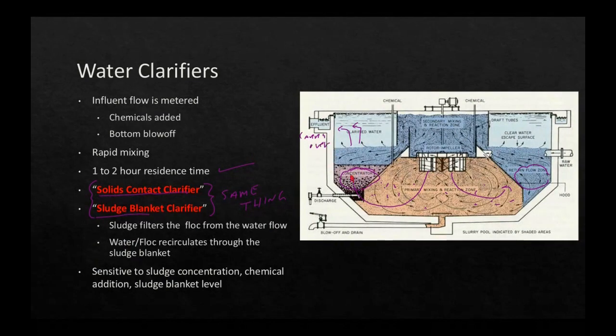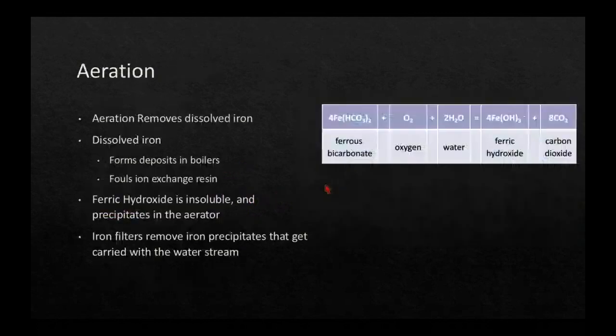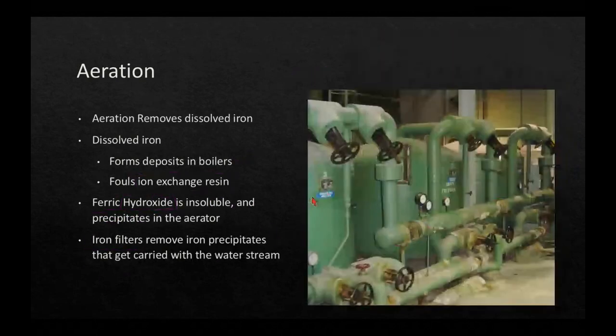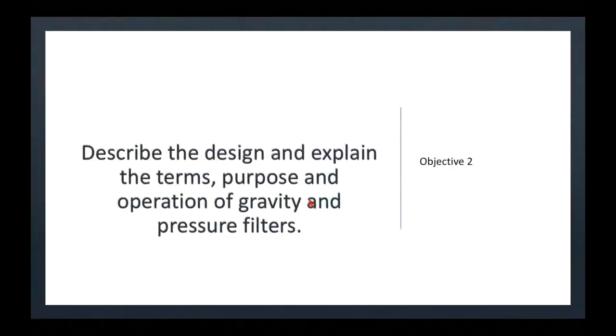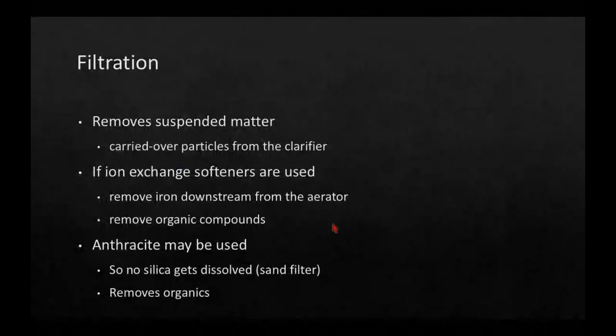So wherever we've got a water clarifier, or an aerator, or a lime soda reactor, we'll filter the effluent afterwards to get rid of any carryover. Which brings us now to gravity filters. Basically anything that's carried over.